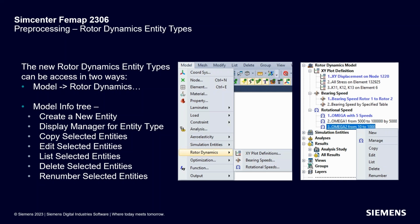So in Femap, there are actually 2 ways to get at the rotodynamics entities. Pretty much universally in Femap, there's more than one way to access different information. So you can go through either the File, Structure, Model, Rotodynamics, XY, Bearing, Rotational Speeds menu, or you can go through the actual Model Info tree, and the entities are listed there as well.